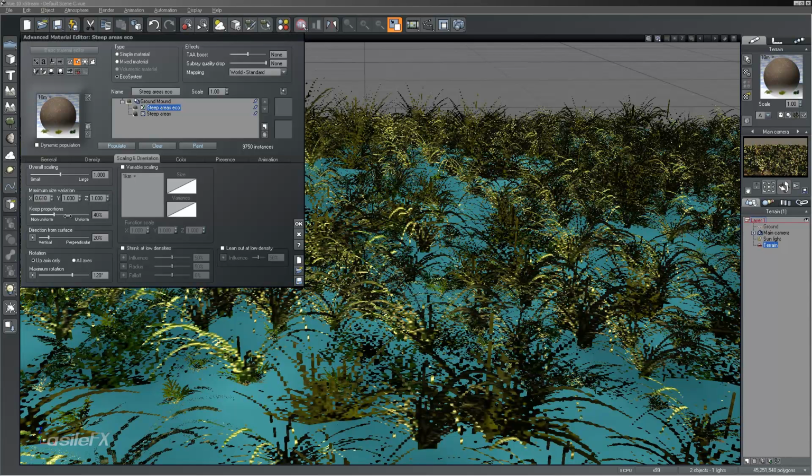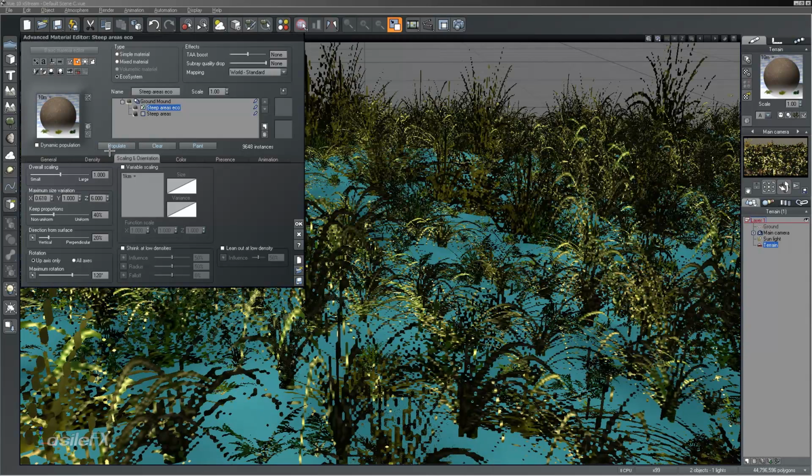If we bring that to a non-uniform value, now we can define the scales for the other axes. So I'm going to change this to 6 for the z in the up and down axis, and now we have the plants being stretched on the z-axis up to 6, and then 0.68 on the x, and 1 on the y.